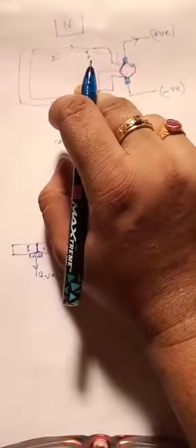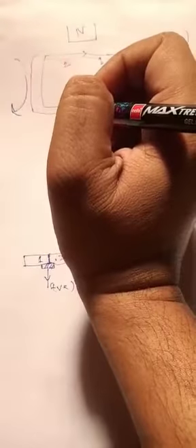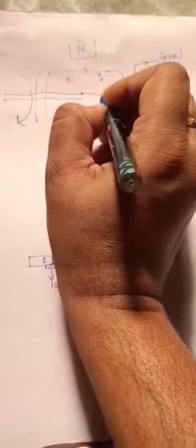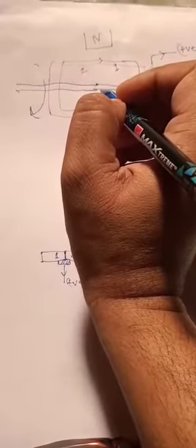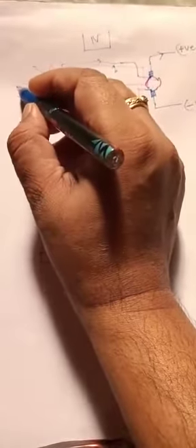In case of a generator, first of all we will consider the first loss. If we are considering this is a generator moving with some prime mover, and this prime mover will be attached with a shaft to this generator armature, the rotor part, and when this shaft is moving, then there will be frictional losses inside the bearings.